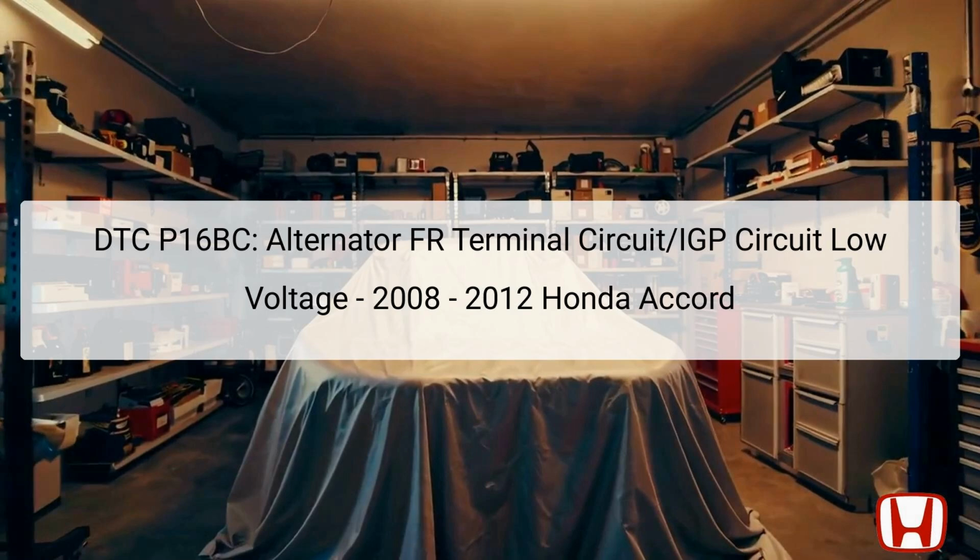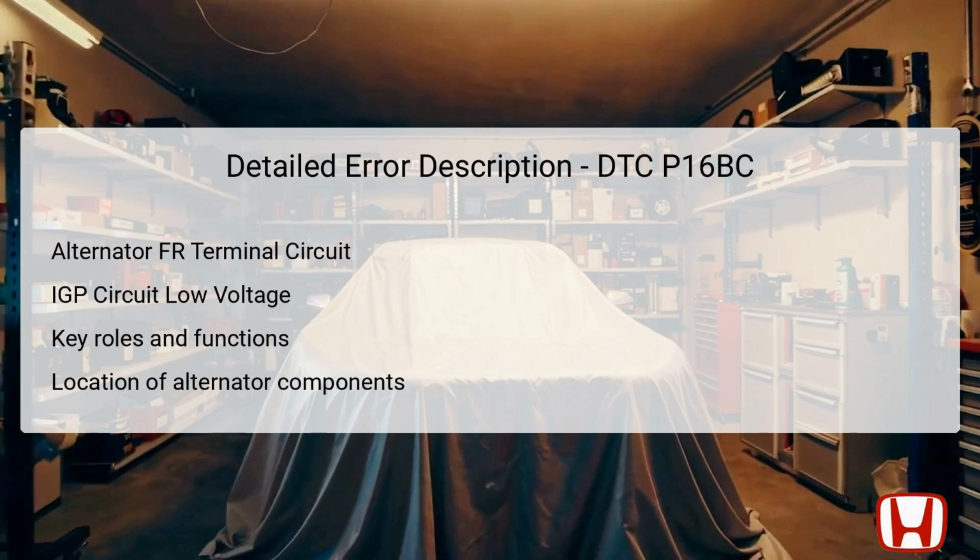issue. The DTC P16BC refers to an issue with the alternator FR terminal circuit or ignition power circuit where the voltage levels are lower than expected. The alternator's FR terminal is vital for regulating the output voltage via the internal voltage regulator, and a low voltage condition can disrupt the entire charging system.